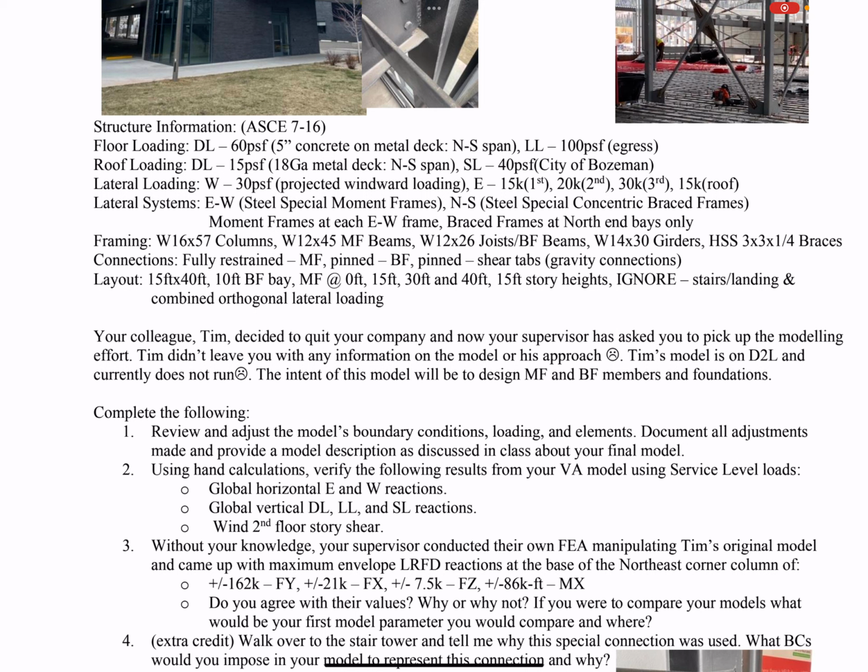That sucks, okay? The intent of this model will be to design the moment frames and brace frame members and foundations, okay? So that's the intent of this model. So if you were designing this, that's what you should be taking into consideration when you are manipulating this, making sure things are right, changing stuff, right? The intent is to look at the frames, and brace frame, the moment frames, and then the foundations, right? So you want to know reactions, okay?